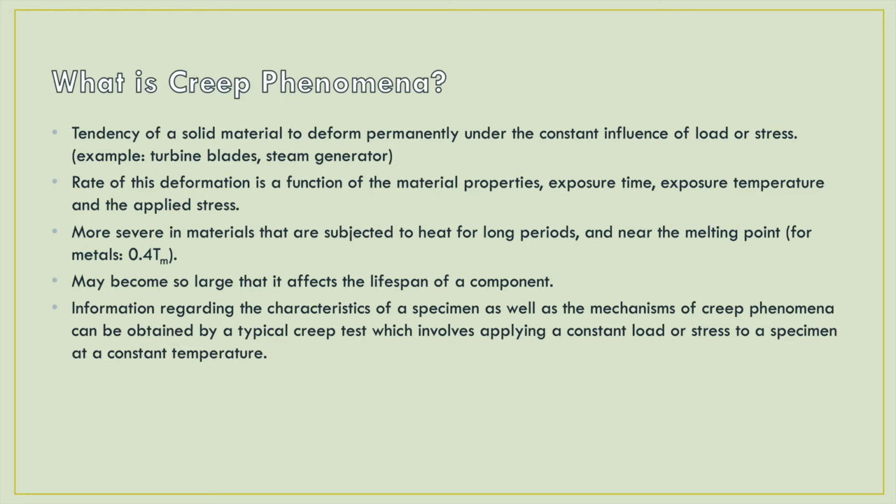Depending on the magnitude of the applied stress and its duration, the deformation may become so large that it affects the lifespan of a component and may cause it to no longer perform its function. Information regarding the characteristics of a specimen, as well as the mechanisms of creep phenomena, can be obtained by a typical creep test, which involves applying either a constant load or stress to a specimen at a constant temperature.